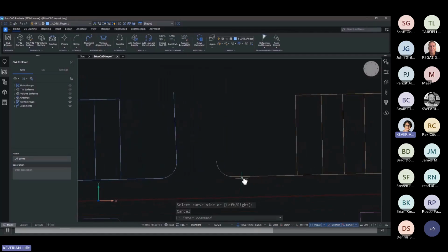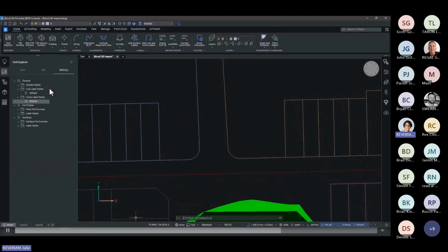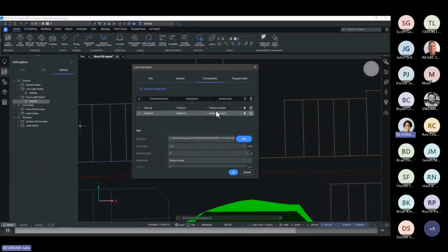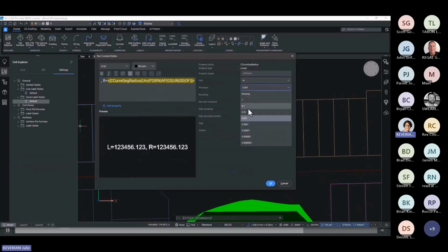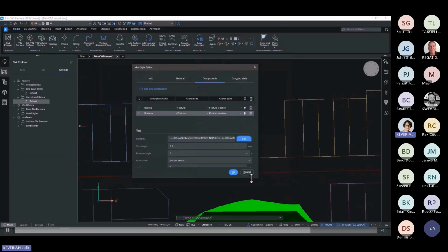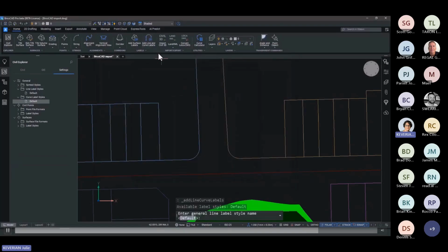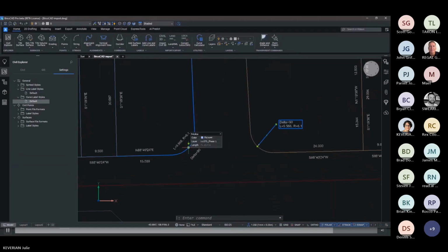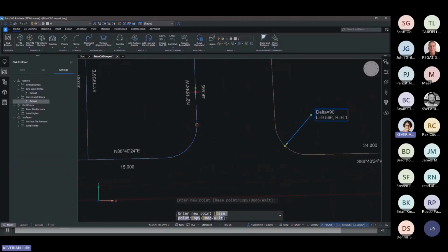Now, survey CAD deliverables usually follow very specific CAD standards, and labels for lines and curves are no exception. Line and curve labels can be quickly created using defined user styles. Then simply select the civil objects you want to label, and they'll be labeled. And these are smart labels. Moving a label from, say, a line segment to a curved segment will change the label style. One less thing for you to worry about. And these labels are also plan readable and viewport scale dependent, ensuring you get to your CAD deliverables more quickly.